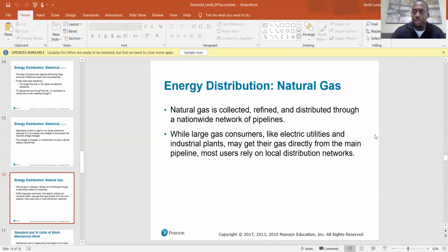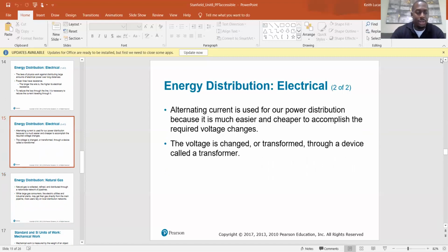So the transformers we talked about in Mod 130, transformers in a split system or in an air conditioning system are usually step down transformers. Our power source to our unit is usually like 120 volts for your indoor unit, your furnace, and then like 240 for your condenser to operate your compressor, condenser fan, and all that. Going back to the indoor unit, you have really both: your high voltage, and then your control voltage.